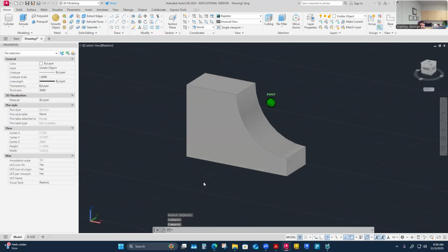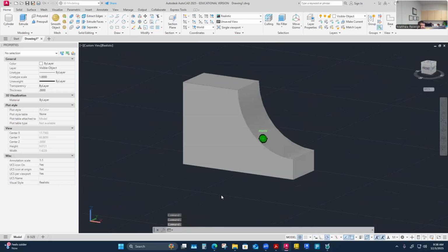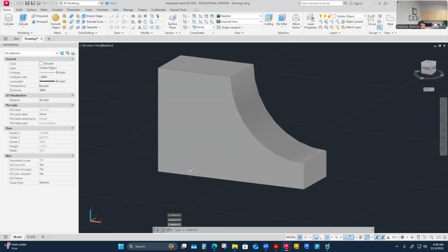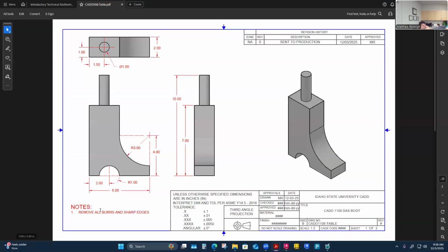Now I'm going to do the other cylindrical cut through this, which is right down here. There's a little heel cut. If I come back to my print here, I need to come over 2 inches from this corner and then draw a cylinder that is 1 inch radius and have that be the one that extrudes through and makes the cut. So I'll reference that geometry with a 1 inch. I think I can do what I call cursor over. Let me try that. If not, I can draw construction material too.